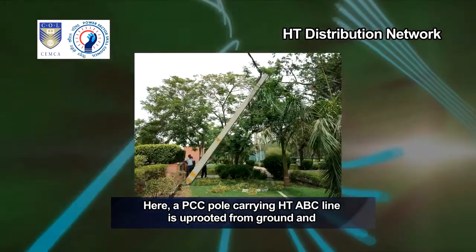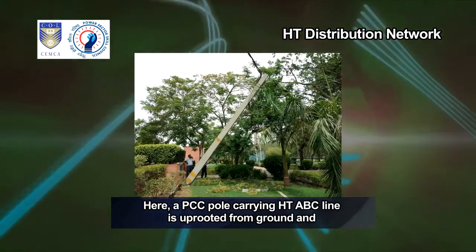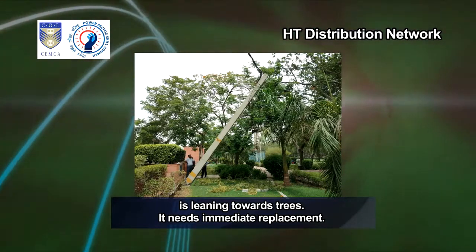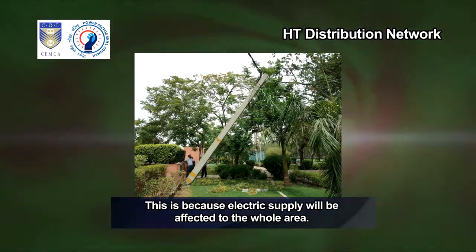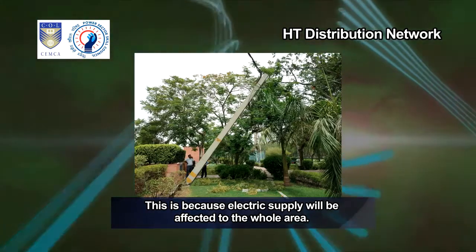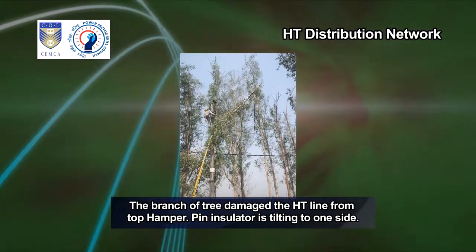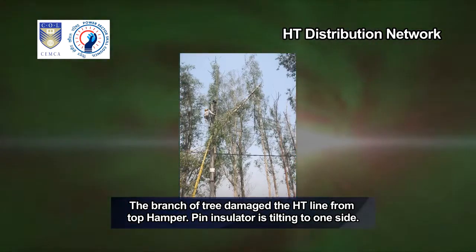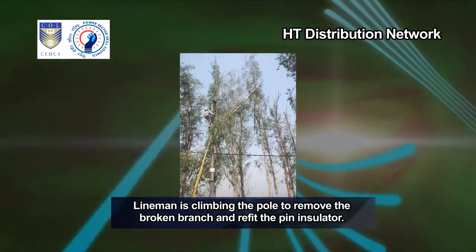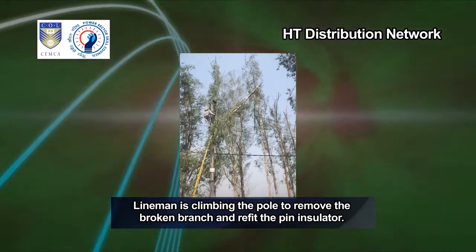Here, a PCC pole carrying an HT ABC line is uprooted from the ground and is leaning towards trees. It needs immediate replacement. This is because electric supply will be affected to the whole area. The branch of a tree damaged the HT line from the top hamper. The pin insulator is tilting to one side. The lineman is climbing the pole to remove the broken branch and refit the pin insulator.